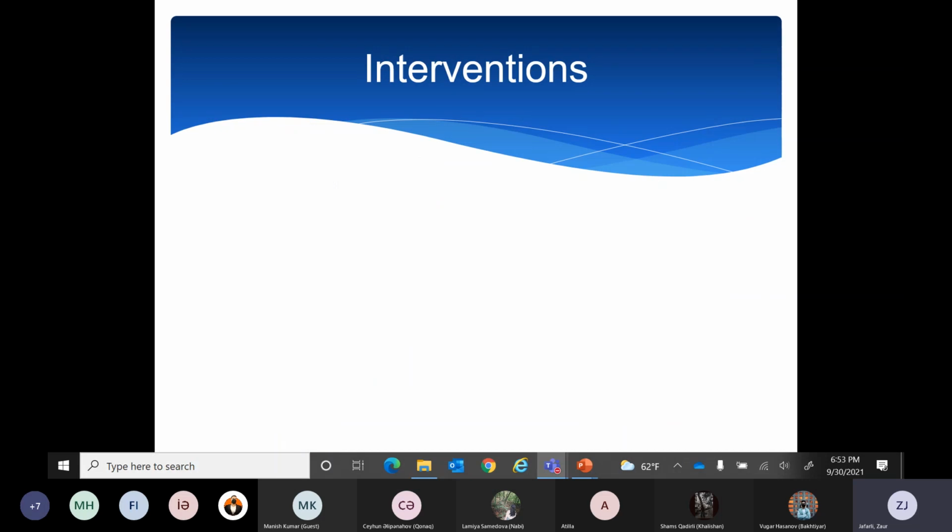Let's talk a little bit about the vertical tree. Sorry, we talked about vertical. Let's talk about a bit of the interventions. As I told in the beginning, interventions are mainly that if anything happens in the well, like after you put it into production, then you do the intervention so that you can intervene and fix it as required.